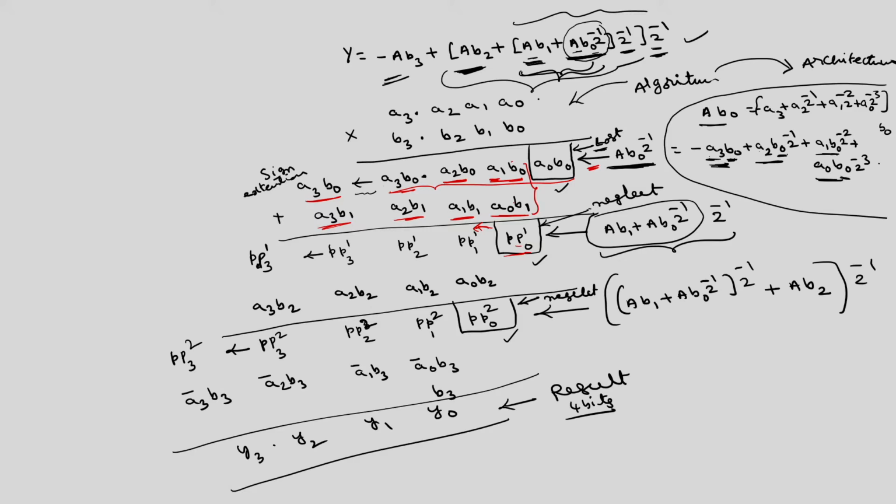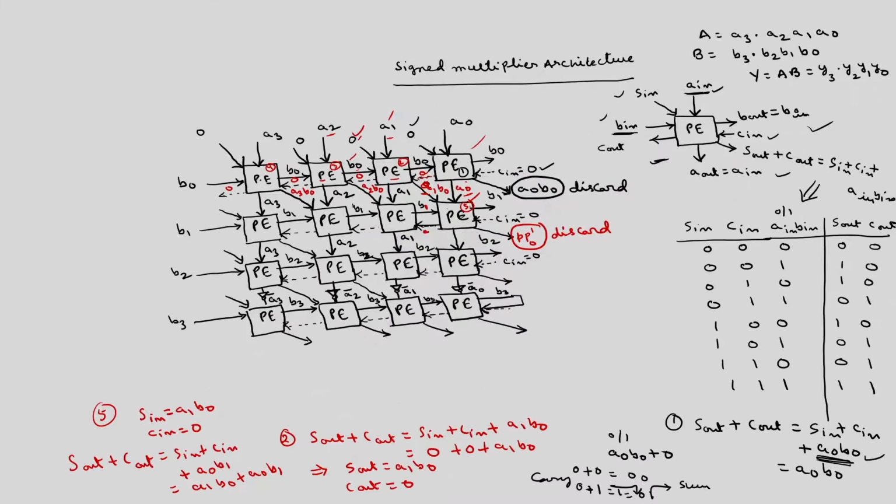Okay. So, now in the third stage we have to add A2 B0, A1 B1 and then the carry of the previous one. The sum of that one is PP11 and the carry again you have to propagate to the next stage. You see here, if I take processing element 6, what is the output? The sum bit. Of course, here you have this to connect to the sum. What is the sum bit of this P6?